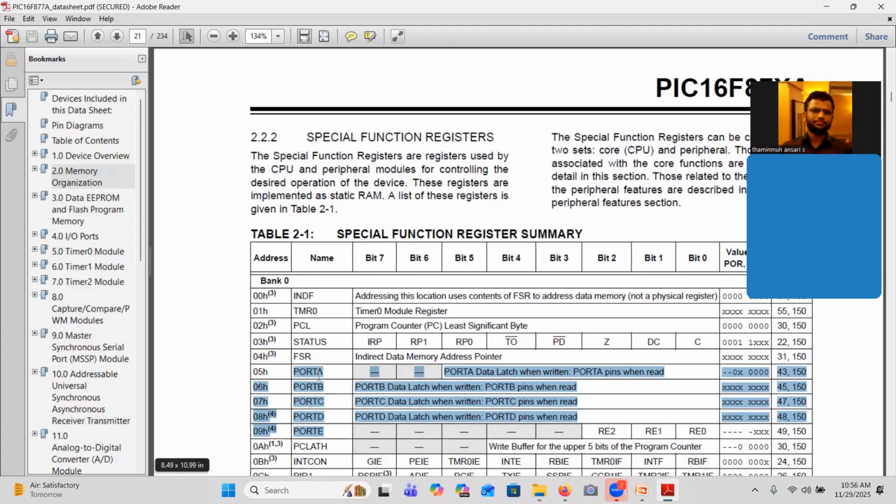So to give high or low voltage to those pins programmatically based on our need, we need some port pins in our microcontroller. Those LEDs are going to get input from the controller. What is the control signal given by the controller, active high or active low? In some circuit designs, if you supply active low, the LED will glow. In some designs, when you give active high, the LED will glow. It depends on the board design.